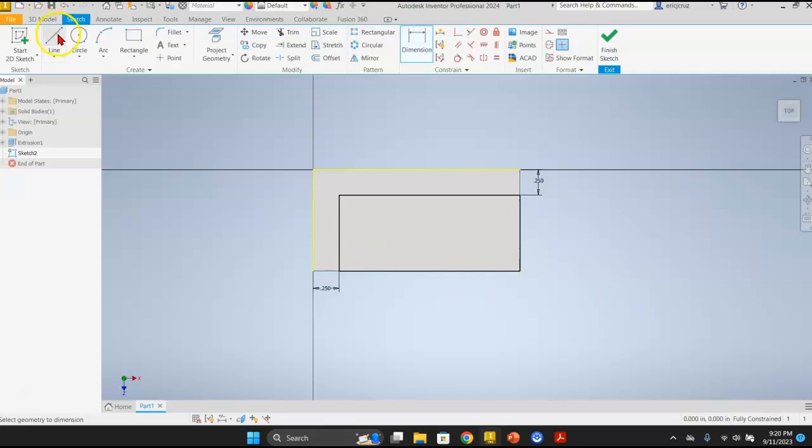Okay, now I'm going to show you a trick that I like to do. I'm going to click on that line tool, and we're going to find the midpoint. So you're going to hover over the left edge here, and it should snap to a dot, and that dot may or may not be green. You can click one time and then move over to the next line, and you can actually go past it because I'm going to show you a couple things. And make sure that you're at 0 degrees if you notice the degrees there, and click and then tap escape on the keyboard.